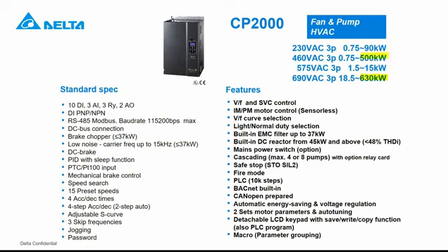And this drive is mostly developed for variable torque applications, which normally don't require a very high overload. So normally fans, pumps, and this type of applications, you normally see that they don't really need more than 100% or 110% overload.